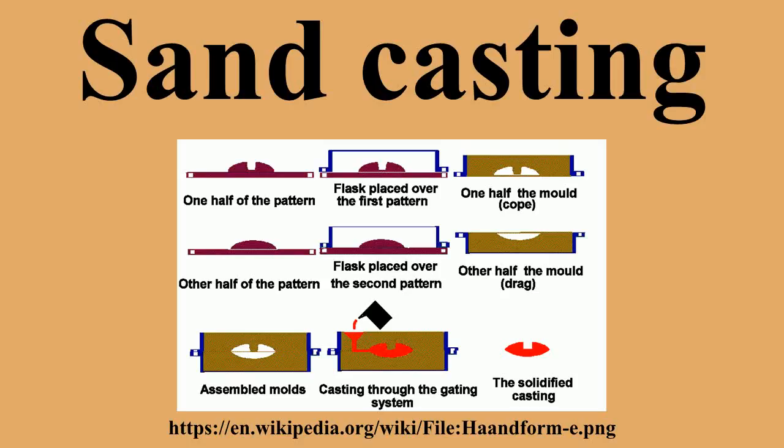Processes. In general, we can distinguish between two methods of sand casting, the first one using green sand and the second being the air-set method. Green sand. These castings are made using sand molds formed from wet sand, which contains water and organic bonding compounds, typically referred to as clay. The name green sand comes from the fact that the sand mold is not set. It is still in the green or uncured state even when the metal is poured in the mold. Green sand is not green in color, but green in the sense that it is used in a wet state.